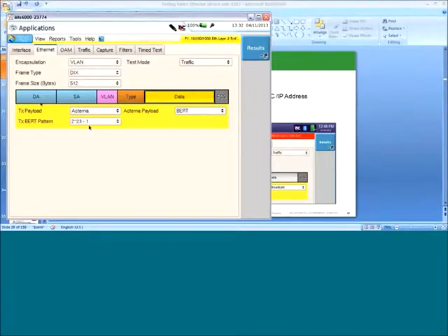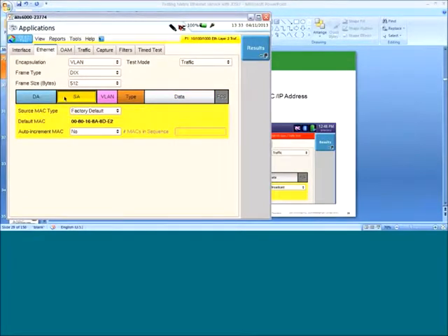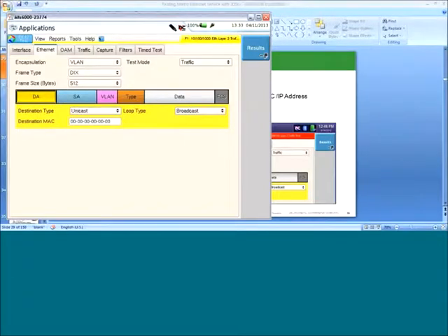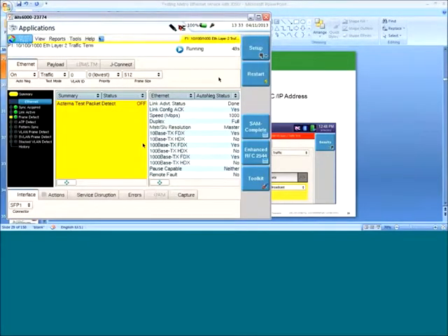Okay. And of course, the most important, destination address, source address. You'll notice that destination has nothing here. So our test equipment will be doing auto discovery, which is really neat because the far end unit doesn't need to be manned. What it allows you to do is basically once you issue a loop-up code, the far end unit will discover it and put itself in loop-up mode. But I'll go into that in a little bit.